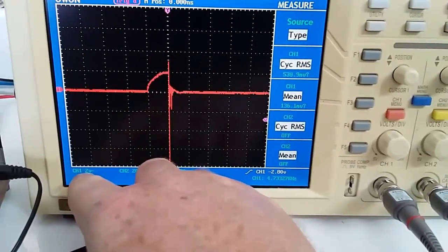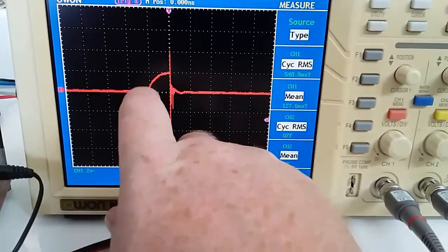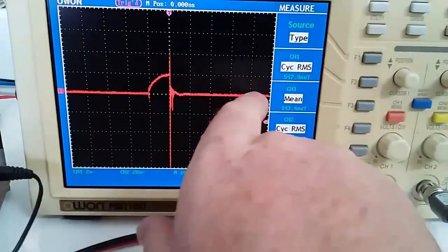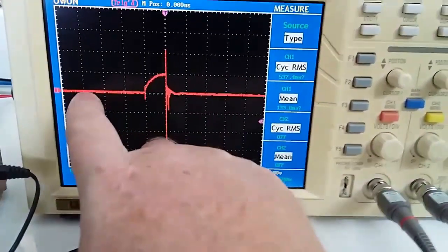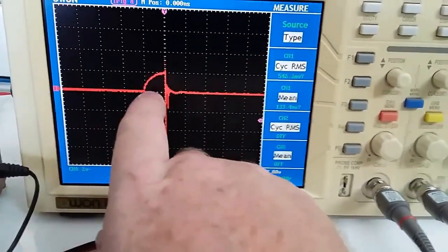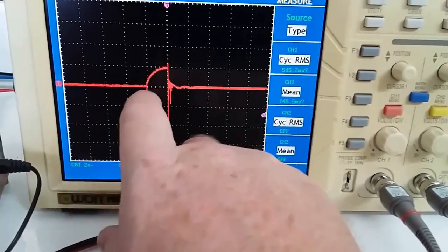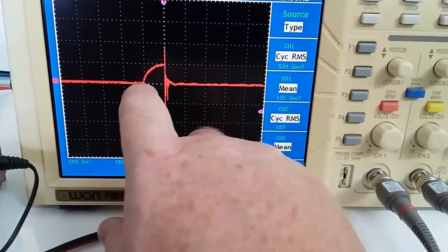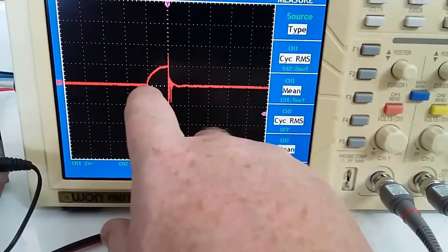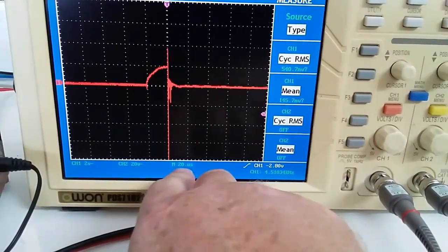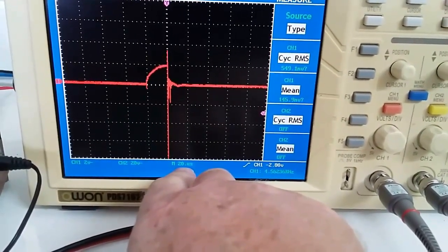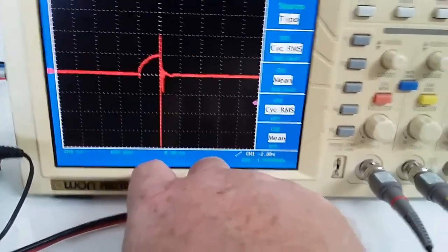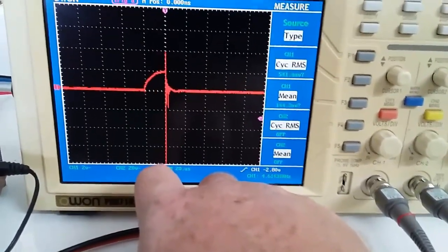So you could say that this tiny little spike here, if you were just to measure just that over time and nothing else, forgetting everything else in time that's out over the side, the off time, you could say that that's 2 amperes of current in that little box there. 2 amperes of current are being delivered to that coil in 20 microseconds. If my poor old brain is working and doing things right today.